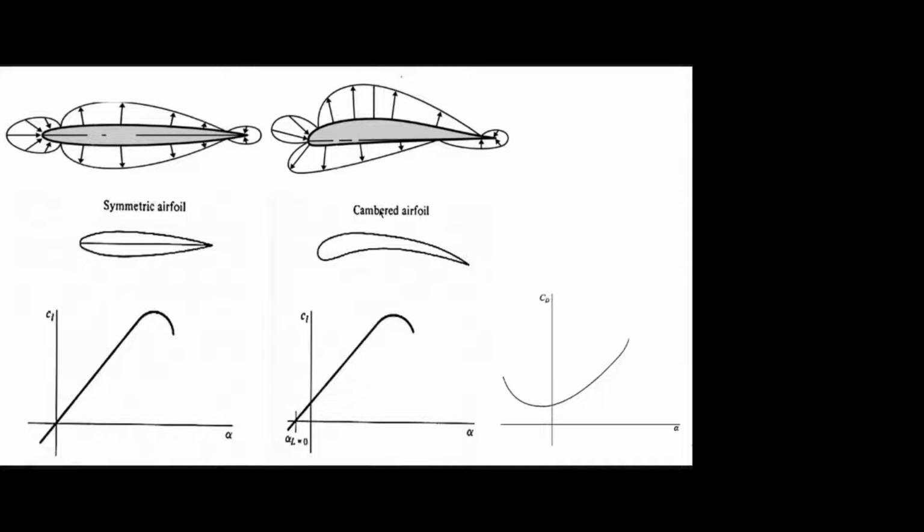And this is the CL/CD curve of the airfoil. As the angle increases, CL will increase, CD will also increase, and everything will happen up to the stalling angle. After the stall, there is a loss of lift, and drag will go like this. Up to that point you can see one curve, and after the stalling, it will go to the maximum.